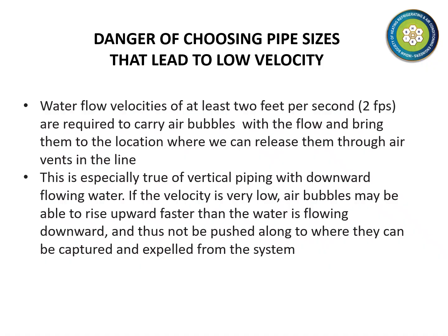Note that very low water flow velocities, that is less than around 2 feet per second, are not desirable. The velocity should be high enough to propel forward any air bubbles to the point or points in the pipeline where they can be captured and expelled.